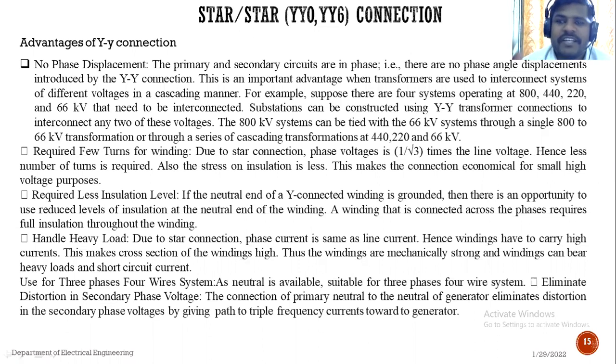Cascade is nothing but parallel, म्हणजे different voltages आपण parallel operation बघितलं थ्री फेज ट्रान्सफॉर्मरचं. We have discussed the parallel operation of three phase transformer. So there are some conditions for operating two transformers or more than two transformers in parallel. दोन किंवा दोन पेक्षा अधिक ट्रान्सफॉर्मर आपण पॅरलल मध्ये पुट करण्यासाठी काही कंडिशन बघितल्या होत्या. Okay, so see, while operating two or more transformers in parallel, the polarity should be the same. Different kVA rating transformers also can be connected in parallel. See, this point is here.